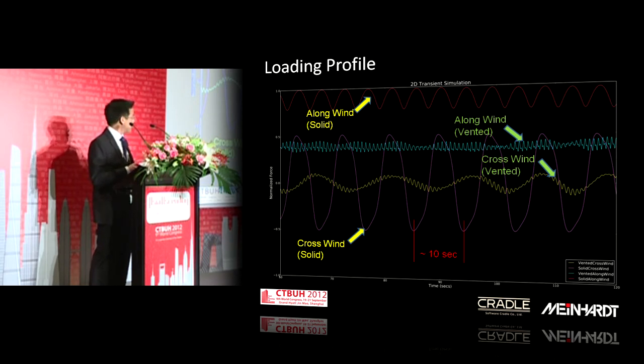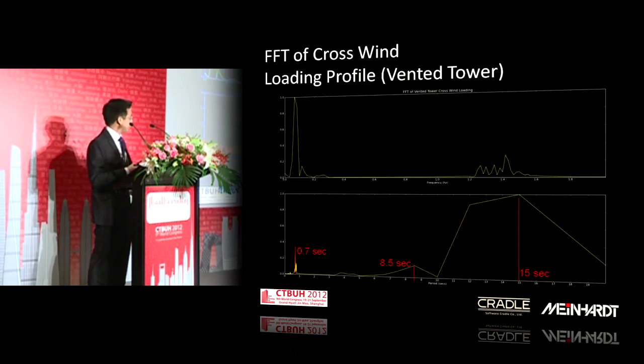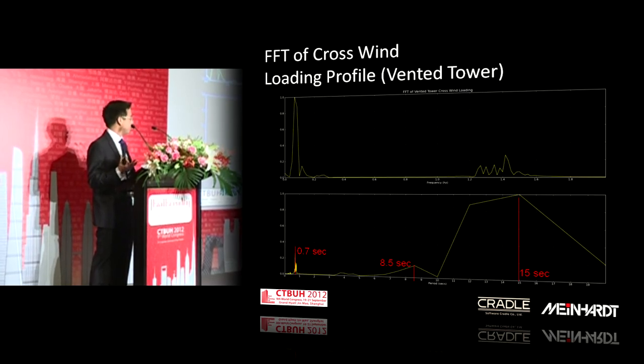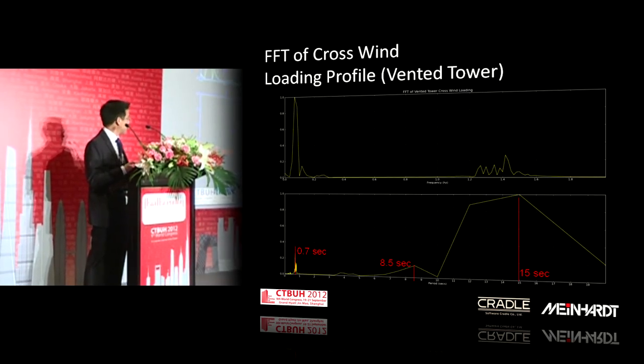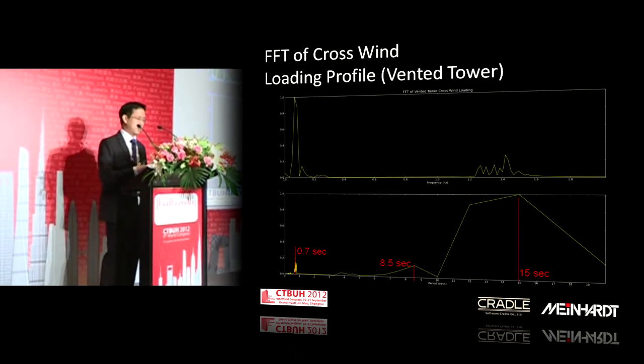So this is good that we're able to pull out the frequencies, but the other thing we noticed in here was there's a long period for the vented case, and of course there's other shorter periods in there. So what we wanted to identify was the shedding frequencies for the vented case, to see what we need to make sure the structure is tuned away from. The long period here is about 15 seconds, and then there's other frequencies in there, and that goes down with the FFT.